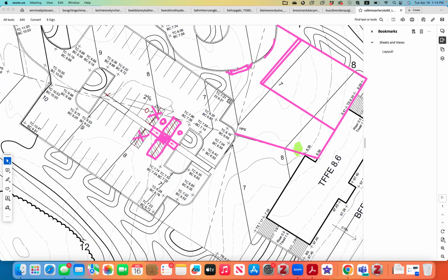You want to try to have the ramp stay away from the swale, because you can imagine water will be flowing along this line. So you would want the ramp to stay away from that swale line. I think this is a better location for the ramp, and you can put the trench drain over there.